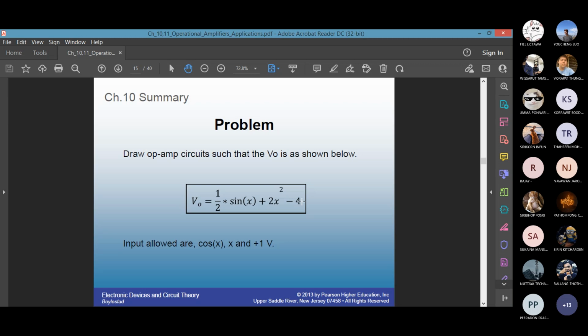or a non-inverting op-amp. If I do not specify the value of resistors or capacitors which you can use, there can be an infinite combination of answers. So it's better to specify some design constraint, especially in the exam. Maybe I will say use only certain value of capacitor or certain type of resistor.